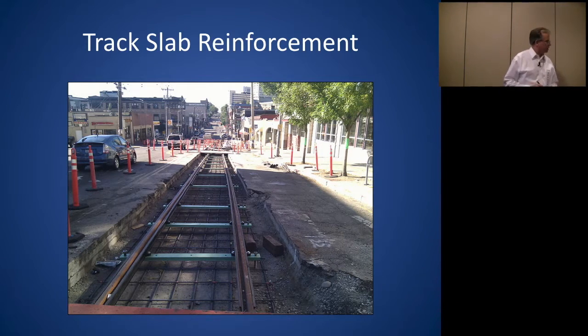You were asking about, is there ties underneath the track in that embedded track? You've got these cross ties here, and then you've got your reinforcing underneath it. This is one type. All that longitudinal reinforcing is going to be electrically bonded, so it's a designed parallel conductor that will maintain, if there's stray current, that's the first thing it's going to hit. We design it to give it a conductor that we can monitor and maintain, and it prevents stray current from getting out from around that. If there's a water line right here, it would help to minimize the amount of current getting on that water line, because we're catching it ourselves in our structure.